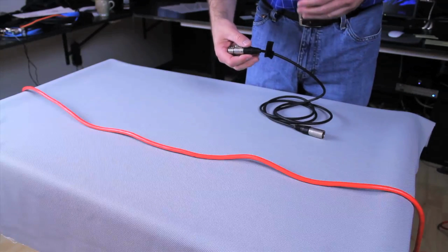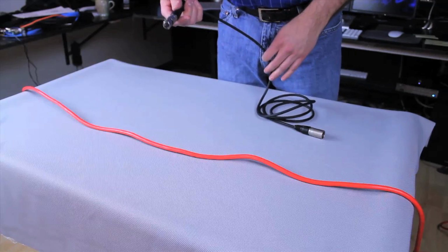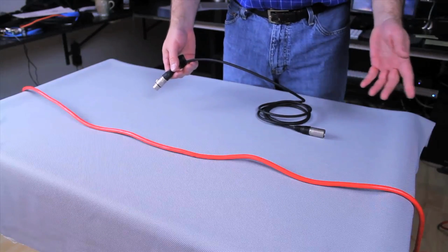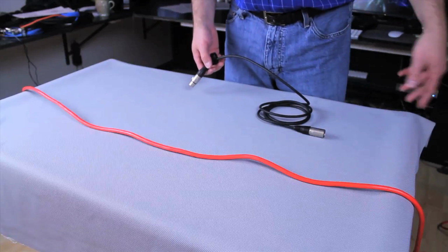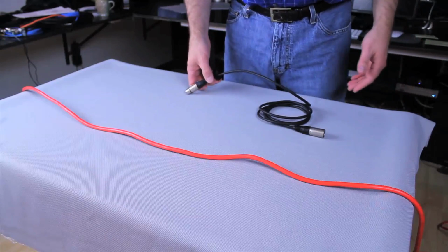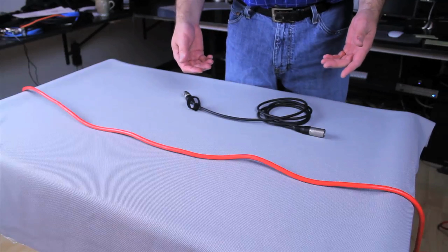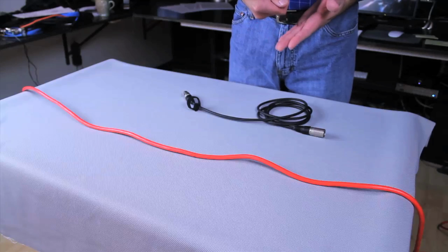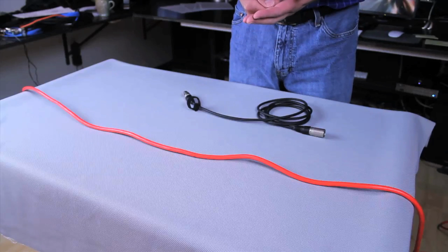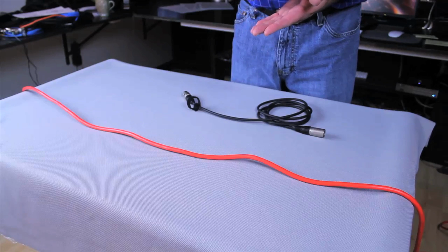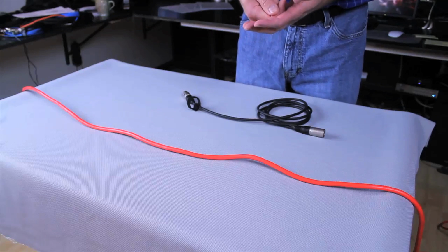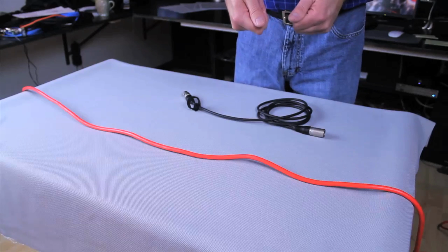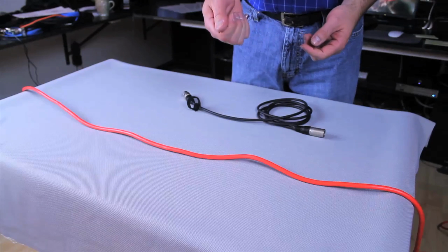The next problem is a troubleshooting thing. A lot of times you're going to plug in to a source, and you're going to have this problem. Let's say you've followed all these rules. There's a couple problems you can have. It can be in your audio equipment. If you're plugged into the wall, you have the 3-prong connector on your AC plug. Go to the hardware store and get what's called a ground lift. It's like a little gray thing you would put on the end, and it just has 2 prongs, and plug that in, see if that helps.